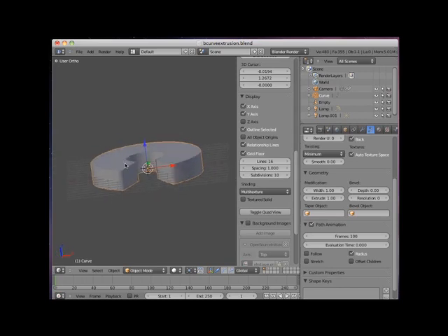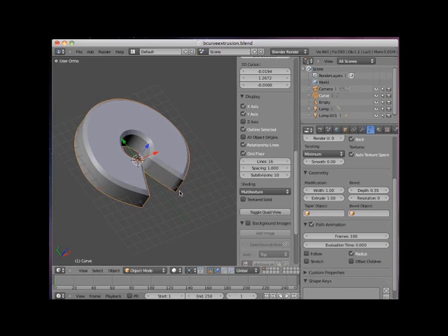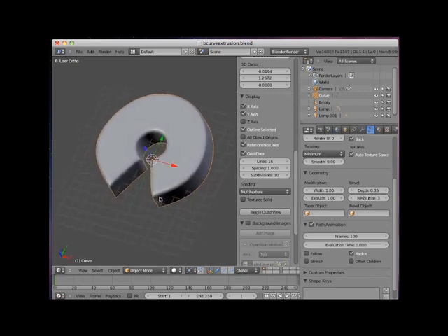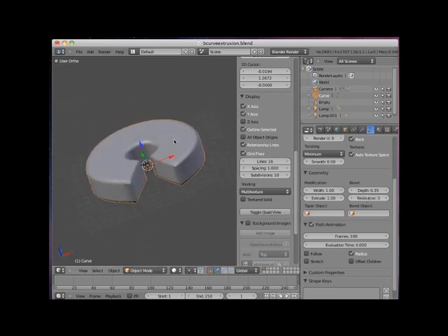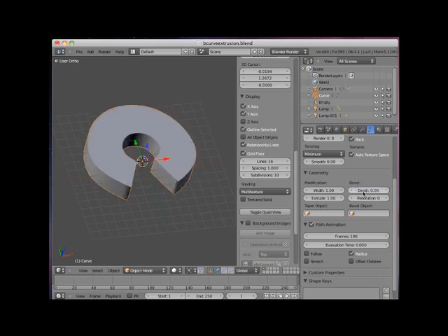I'll add a bevel to the surfaces by setting the bevel control to 0.35. I can round off that bevel by increasing the bevel resolution. I'll set the bevel resolution at 3, which nicely rounds off the bevel. Now I'll set the resolution back to 0, and the bevel back to 0, and the extrusion back to 0. And I'll go to top view.